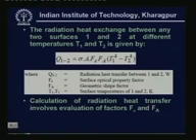So, basically it is a function of emissivities of the surfaces, and you also have a factor Fa, which is known as the geometric shape factor or configuration factor, and T1 and T2 are obviously surface temperatures of 1 and 2 in degrees Kelvin, that means in absolute temperature scale. So, the major problem in radiation is the evaluation of the factors F epsilon and Fa. Normally we know the temperatures T1 and T2, and we also know the surface areas, etc. So we have to find out the factors F epsilon and Fa.